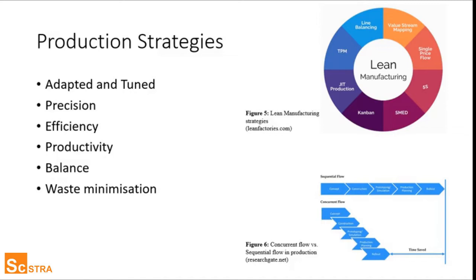As a next strategy, we have the family of lean production that set rules to eliminate waste, increase productivity, and efficiency by minimizing the non-value added activities throughout the project. Lean production rejects relocation of material, goods, machinery, and staff, prohibits material storage and buffering the goods. Since setup time is not considered a value-adding activity in a production line, it should be reduced as much as possible.